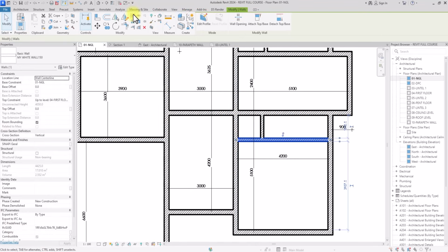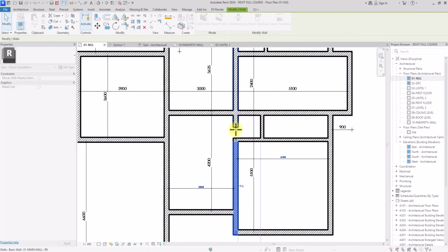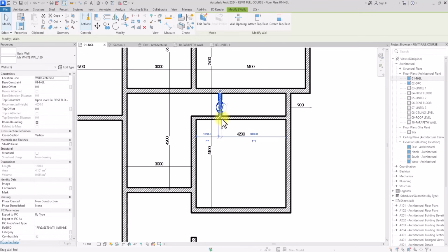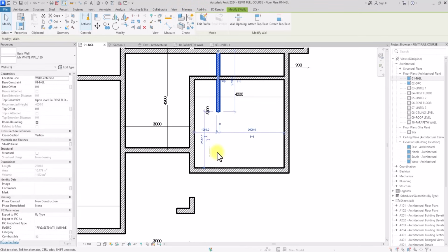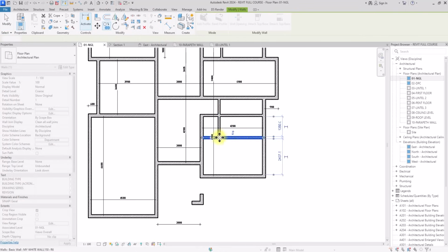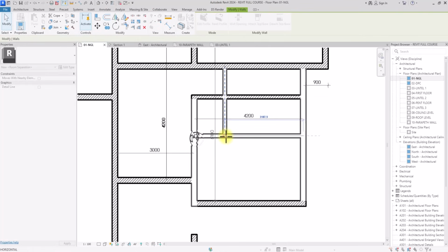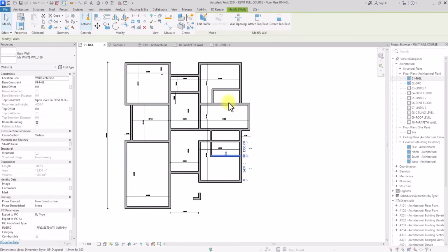I'm going to click on this bevel to separate this wall, and I'm just going to drag it here. So now I'm going to extend this wall this way to create a convenience for this room here as well. Then I'm just going to click on this wall and copy this. So locating the 2 conveniences in proximity so piping can be easily done.